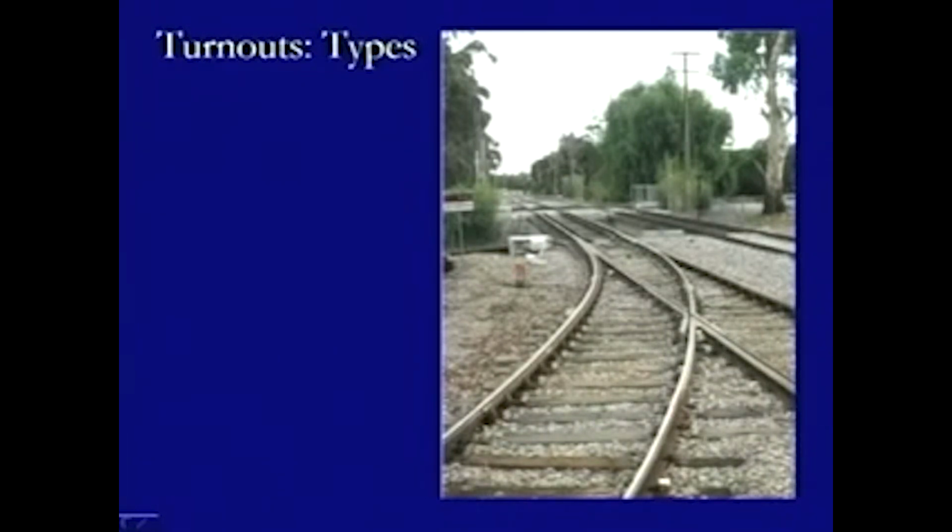So, this is what we can see, there is a crossing, we have a point and a splice rail provided here, this is the wing rail being provided on this side, this is a wing rail provided on this side, this is the curved section, this is the straight section, this is another curved section here. So, we have the inner or outer curved section, we have the inner or outer straight lead rails, and then on this side we are providing the extra safety features here in the form of maybe the check rails.